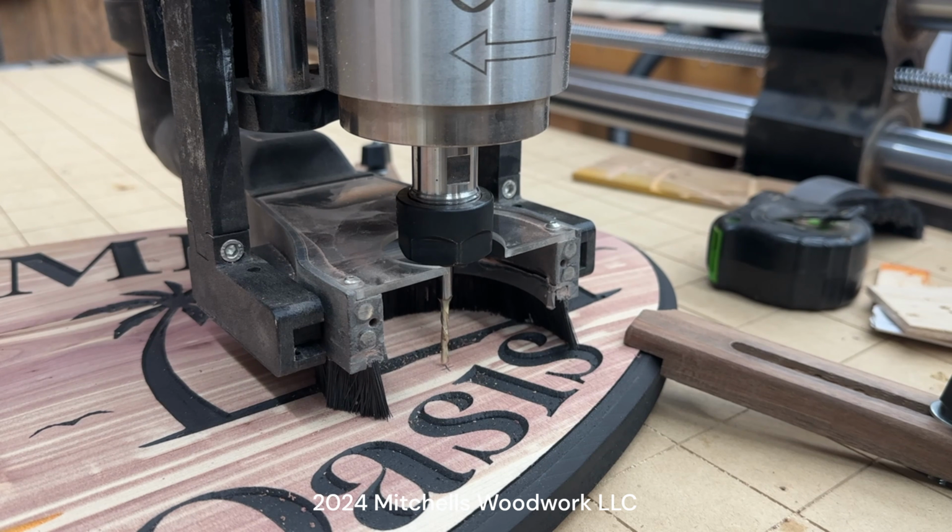So I just decided to switch over to a 1/8 inch bit in VCarve Pro and run the preview, and it did fine. So that's what I did. I have switched over to the 1/8 inch downcut. I have set my zero. I have set my XY. Everything is good to go.